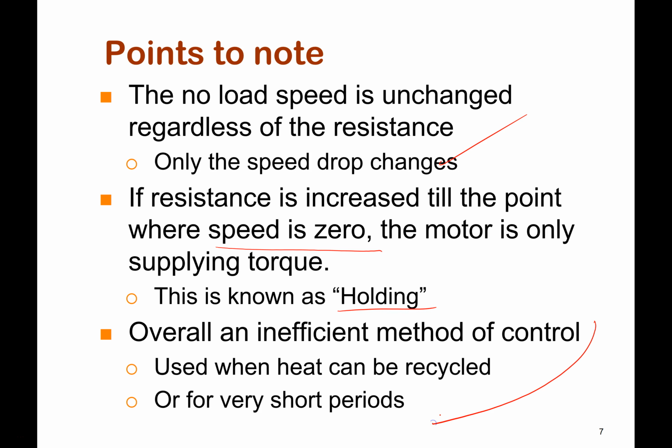And overall, this is a very inefficient method of control, because as we add resistance into the circuit, the amount of losses increase. So remember, the amount of torque depends on the amount of current. So if you have the same current but you have a greater resistance, you're going to get more losses. So it's not a very efficient method for control.